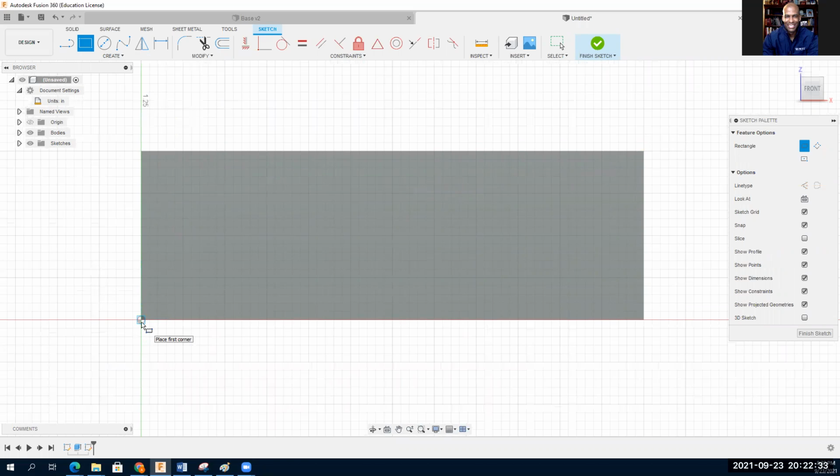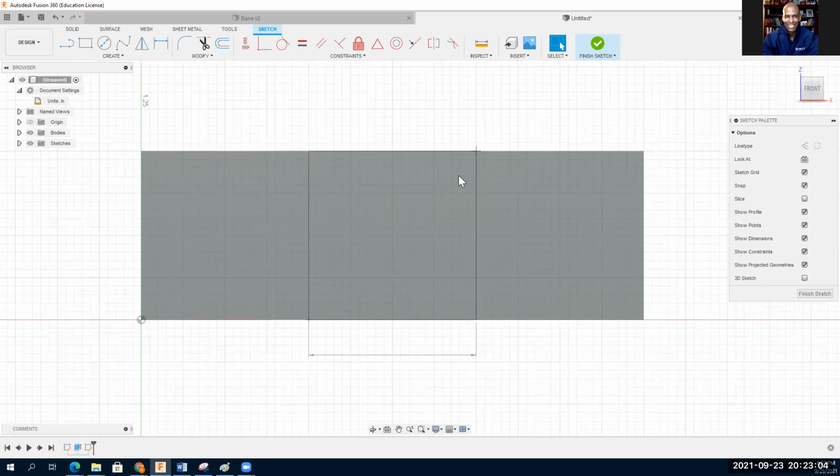So as I scroll along, hover my mouse along the x-axis, the program will lock at a 1/2 inch as well as 1 inch. So this is where I'm going to start my drawing. So I'm going to click, hold, and drag, and I'm going to let go of my mouse, and I am going to manually type in my dimensions of 1 inch, tab, 1 inch, and I'm going to hit enter.